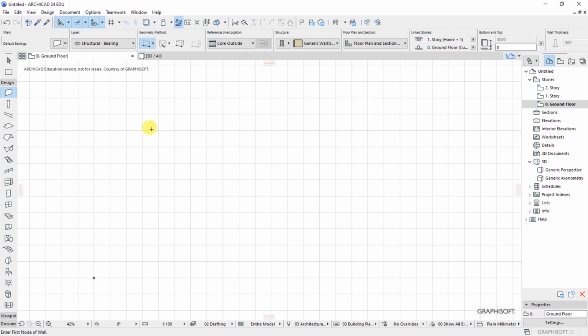The answer is I'm looking at where I'm going to place my columns. We have intersections between walls. That is where I'm going to have my structural members. Basically, where these lines intersect, that is where we have the center for the columns.